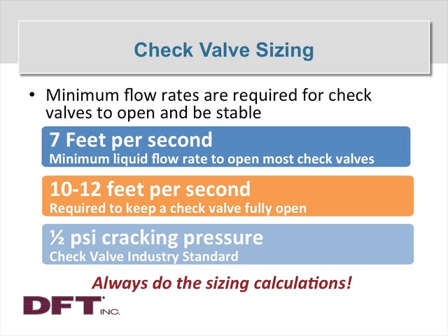And if you've decided, for instance, that the best check valve style is, say, a swing style check valve, then consult with the manufacturers that are of interest to you for that particular style of valve. If they're technically sound, they're going to confirm these guidelines and maybe refine them just a little.